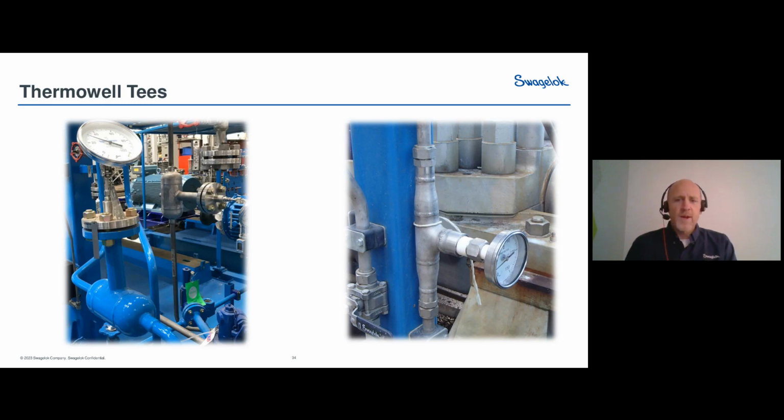Now, traditionally, thermal well tees are welded monstrosities, kind of like what you see here, and I don't mean that in too negative of a way, because certainly they're good construction and certainly they're effective, but they are a lot of work, and as a result, they're fairly expensive. If you look at the thermal well tee on the left, look at the number of welds that you would have. You'd have a weld up here, one, saddle weld two, three, four, five, six, seven, eight, at least eight welds on this particular thermal well T. Then you've got the thermometer that goes down into the thermal well, which is attached on a flange. So a lot of work went into building this thing, and then installing it, of course.